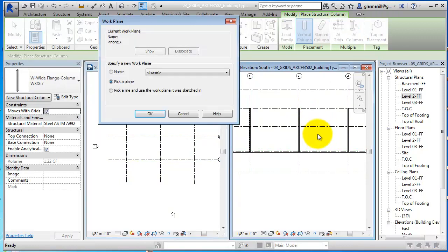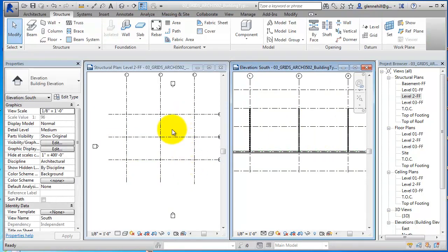Okay. There is a way to copy. The problem is that it's very difficult because Revit restrains you from copying things in all 3 cardinal directions at one time, the X, Y, and the Z. It prefers to allow you to only copy in the X and Y direction, or the X and Z, or whatever it might be.